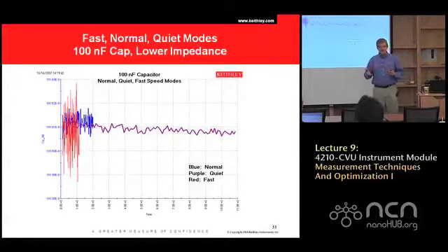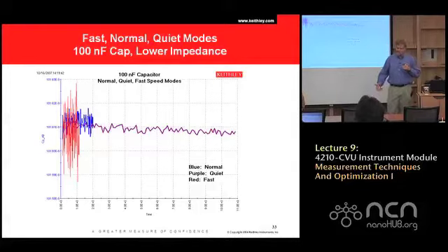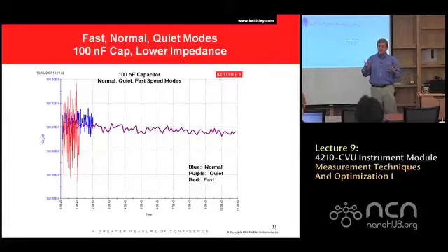Again, I see this happen all the time. Because the graph in this instrument is auto-scaling, if you have it set up to do that, oftentimes we will see it take a really low noise measurement but blow it way up on the scale, and if you visually look at it you go, why is that measurement so noisy? Well, it's not noisy, it's just the scale. The scale bites people all the time on this instrument, so be aware of that.